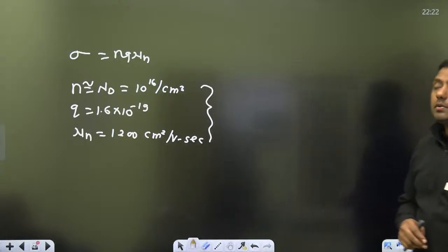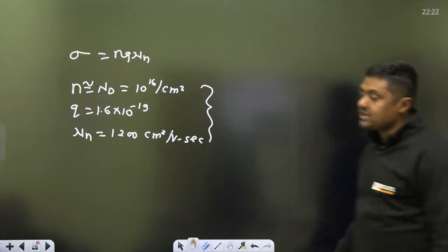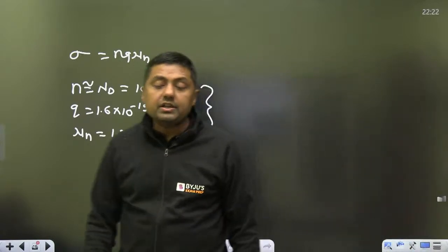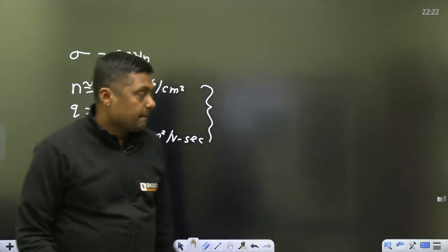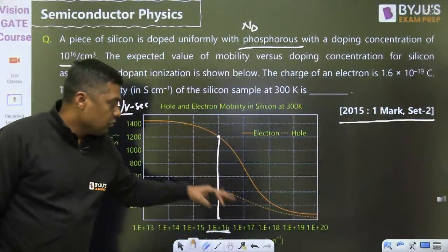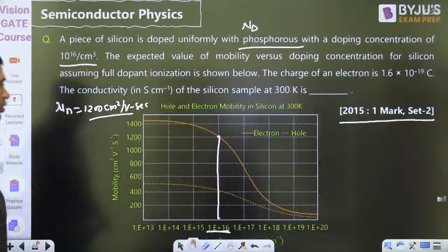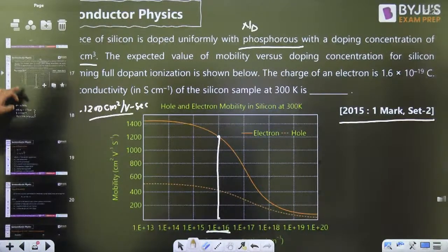So yes, Amrita, a negative temperature coefficient means temperature increases, mobility decreases because of lattice scattering. It also decreases because of what? Impurity scattering at high temperature. Okay, impurity increases, mobility starts decreasing. Mobility starts decreasing, guys, because of the impurity. That is the case for constant temperature also. So this is a very important point.